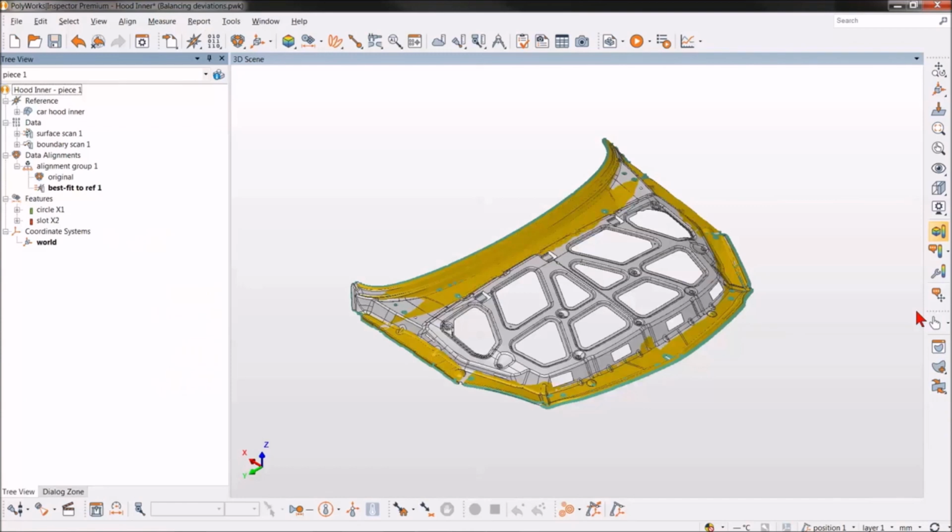If you are inspecting parts with symmetrical features, you're probably trying to align them so that you get equal deviations on opposing sides of a symmetry axis. Reaching that goal is difficult with traditional alignment tools since the symmetry axis is in fact an imaginary line that must be constructed. In this webinar, I will demonstrate how you can build a reference target alignment that uses dependent features constructed from different measurement objects to establish that symmetry line.